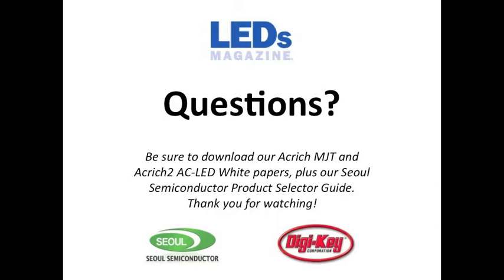Make sure you understand the reliability of their product. Make sure you're looking at hopefully LM80 data and really understanding their product. Make sure you're testing it, doing over temperature testing, high current testing, and stress tests to make sure that it's going to be what you need. But just be very careful when you're looking at those products.